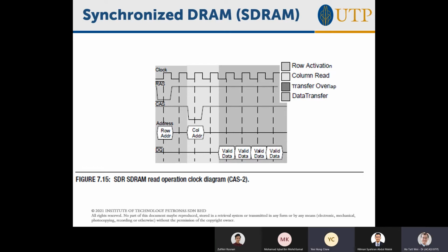Okay, understand. Good. Now, how is SDRAM different from DDR RAM? DDR stands for double data rate dynamic RAM. Nowadays, the memory in your computer is all DDR. The only difference is that instead of reading the data at the positive clock edge only, in DDR the burst data is set out at every clock edge, on the positive edge and the negative edge.